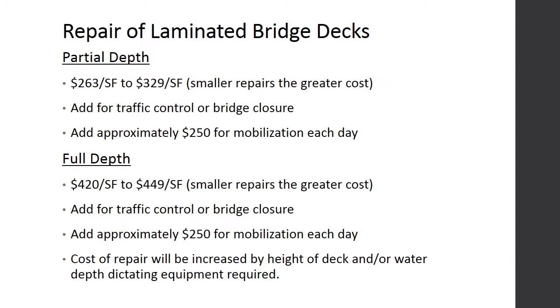In each case, additional costs for traffic control or a bridge closure will need to be added, along with approximately $250 per day for mobilization. Also, in the case of a full-depth repair, the cost may be increased by the height of deck and/or water depth dictating the equipment required.